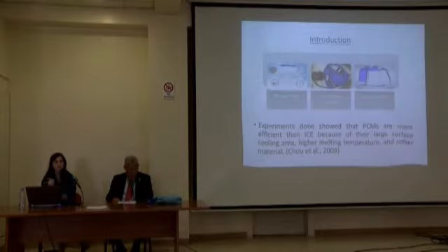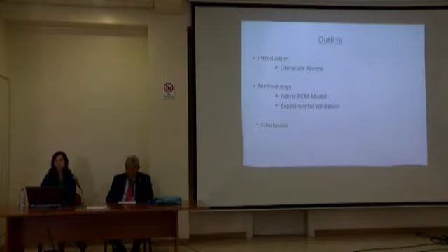These salt PCMs, they could be either incorporated as microcapsules inside the fabric, or they could be placed in small packets. But the microencapsulation wasn't very successful because of the volume and heat capacity constraint. So in this work, we will focus on the PCMs that are placed inside packets, and these packets will be placed in pockets in the cooling vest. So I'll start by giving some of the previous work, and then I will present the developed fabric PCM model, this mathematical model, and then the predicted results will be validated by experiments.